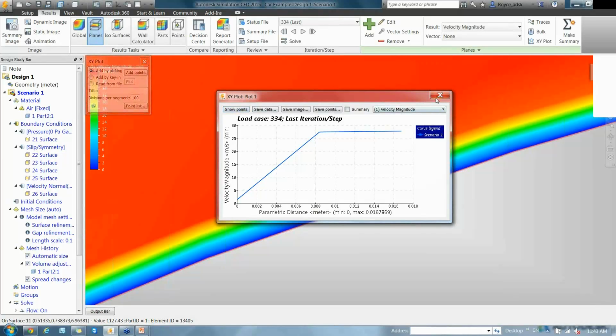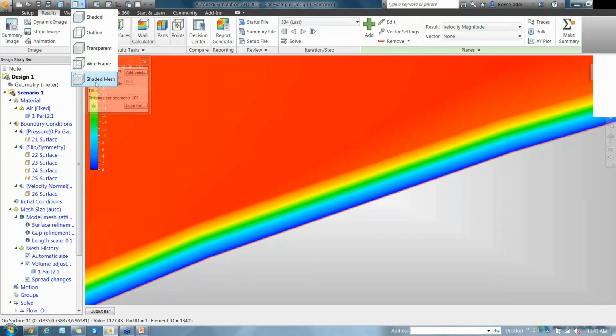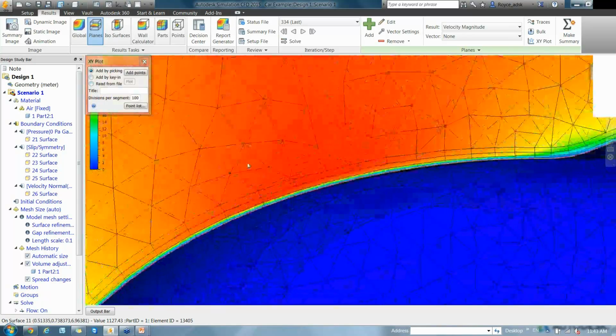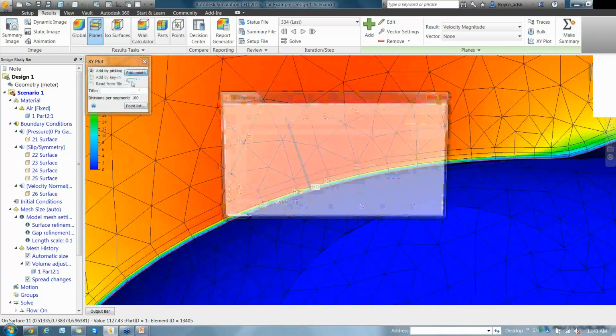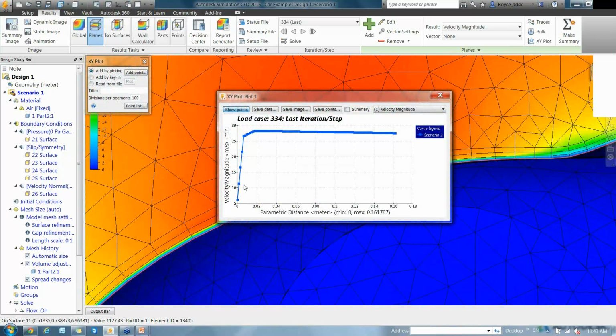You can start to see, actually maybe I should look at the mesh, make sure I get outside. Yeah, there we go. You can see the first layer, second layer, and the third layer is probably right in here, and then the core mesh. So this Y plus is a measurement of a non-dimensionalized distance to this node, in essence, and how that relates to the velocity.